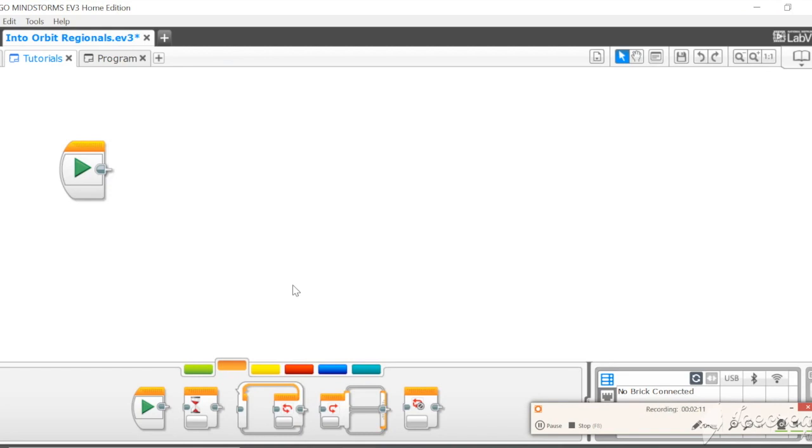Now before we continue, we have to talk a little bit more about the gyro, because there's another major problem with it in the case of our program, and it's that the gyro doesn't reset back to 0 if it goes over 360 degrees. This means that if you try to turn over a full circle, the number that you are given will continue to climb instead of going back to a number that is simple to use. To solve this, we use a mathematical formula known as modular.